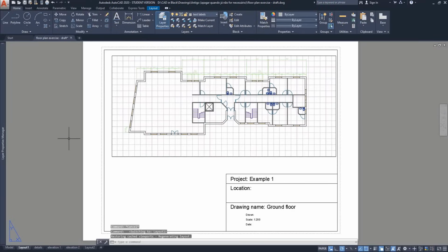Annotation in AutoCAD. In the next part, we will focus on how to insert annotative text and dimensions. It's simple, we just need to play a bit with scales in the workspace. The text height that we insert for our text is actually the real size that will be printed. For example, in Layout 1, I want to write text in this viewport with a text height of 0.005 meters.